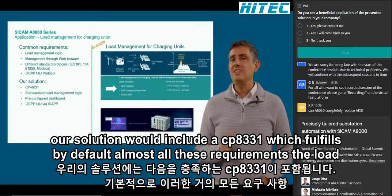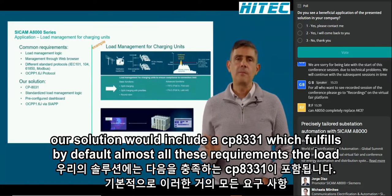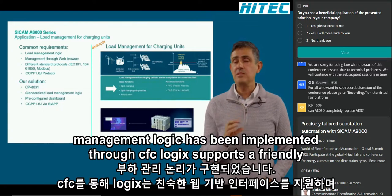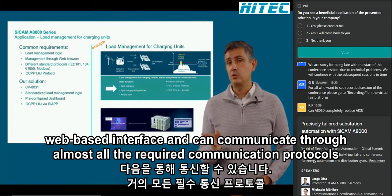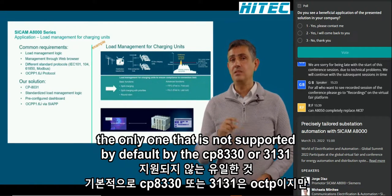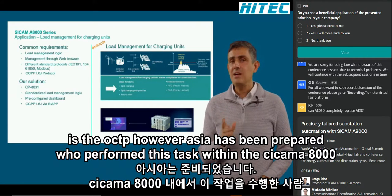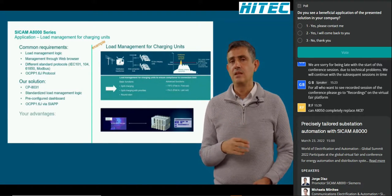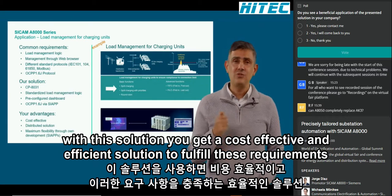Our solution would include a CP8031, which fulfills by default almost all these requirements. The load management logic has been implemented through CFC logics, supports a friendly web-based interface, and can communicate through almost all the required communication protocols. The only one that is not supported by default by the CP8030 or 31 is the OCPP. However, a CAP has been prepared which performs this task within the SICAM A8000. With this solution, you get a cost-effective and efficient solution to fulfill these requirements.